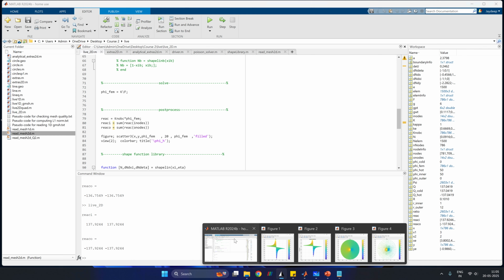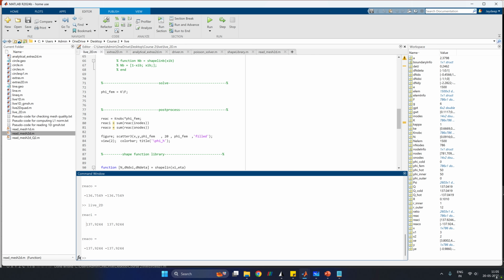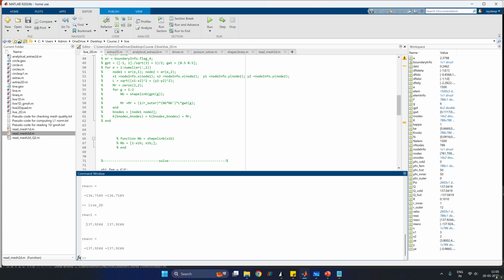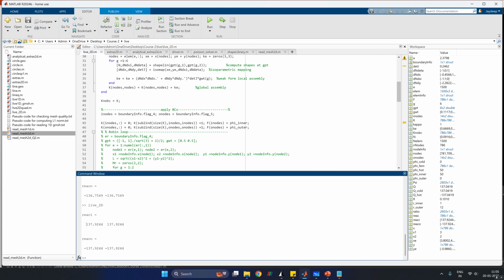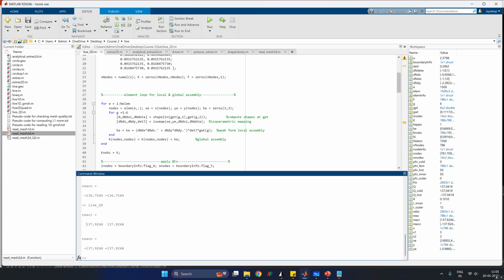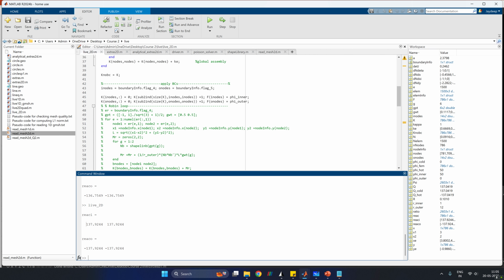And I'll be providing scripts in Julia, Python, and MATLAB, and in those scripts I will also be providing the code in sparse assembly, right? So sparse triplet assemblies. So this will allow you to really use small meshes, and when you use sparse triplet assemblies in MATLAB, you can easily go to 1 million DOFs as well.